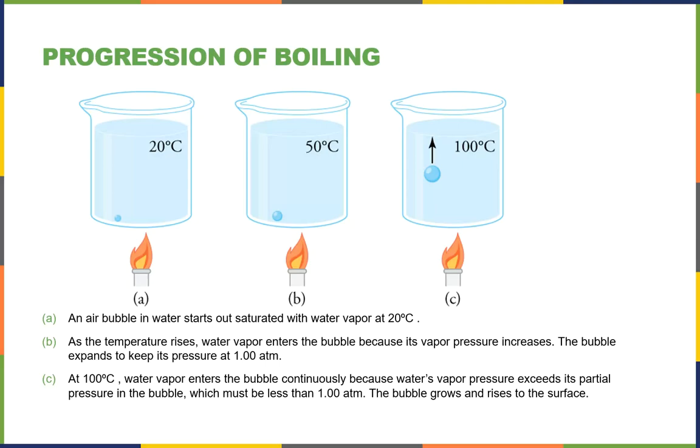It nucleates bubbles. It traps air on the sharp edges. And so you have little bubbles to start with. So as the temperature increases, you have bubbles that then can grow. If you have bubble-free water, you can superheat it. You can heat the water to above boiling temperature because you have no bubbles that are growing. And then all of a sudden, you have a bubble form, and it makes a whole bunch of bubbles form, and the whole thing blows up.